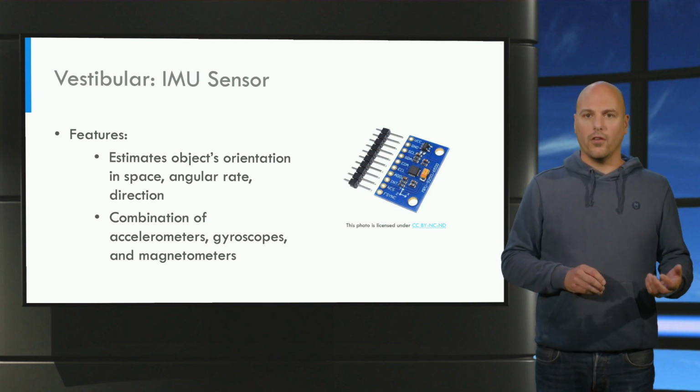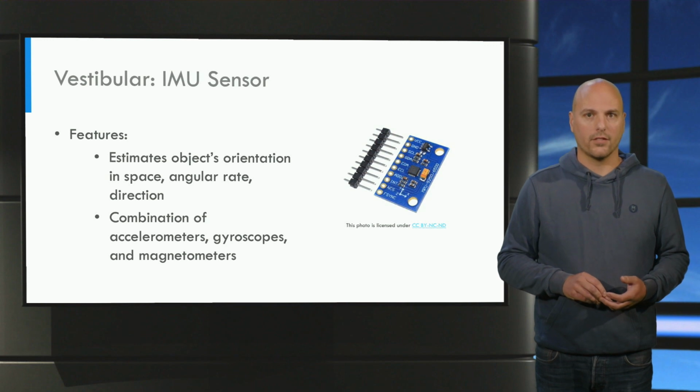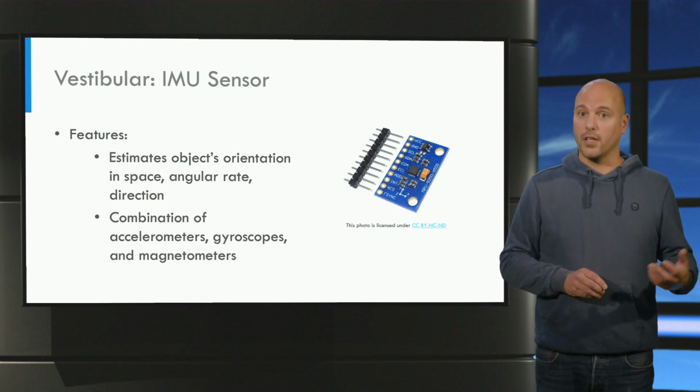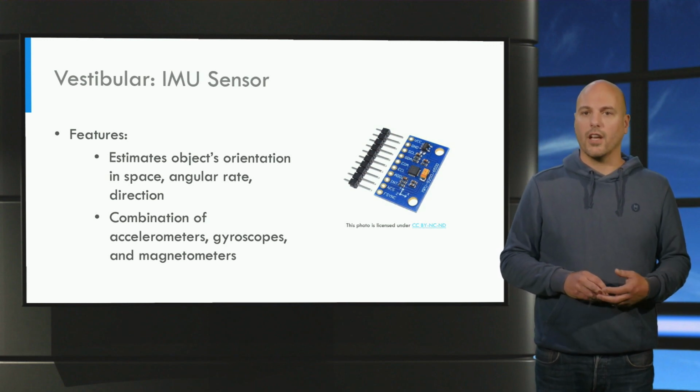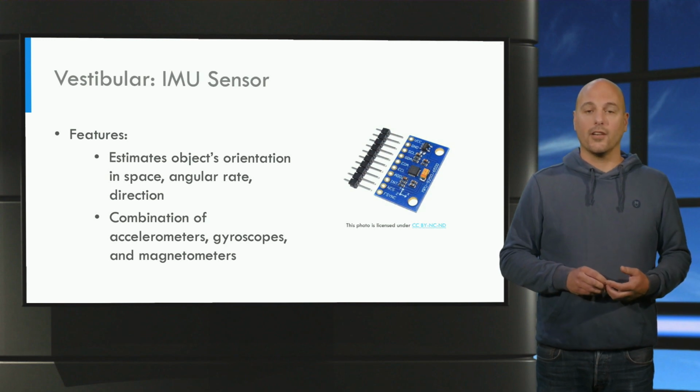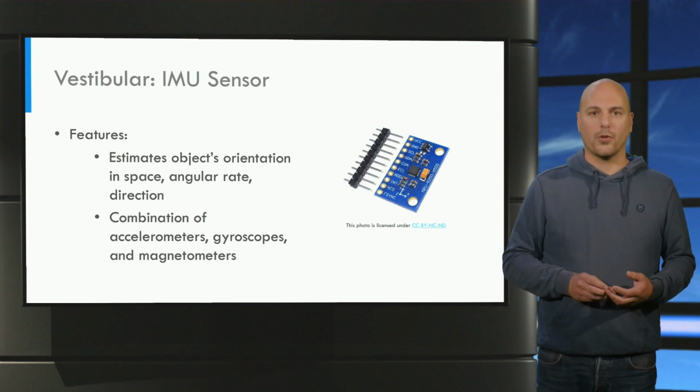Another commonly used passive sensor in robotics is the IMU, or Inertia Measurement Unit. This device often consists of accelerometers, gyroscopes, and magnetometers to deduce its orientation and acceleration. In robotics, this is mostly used for proprioception.